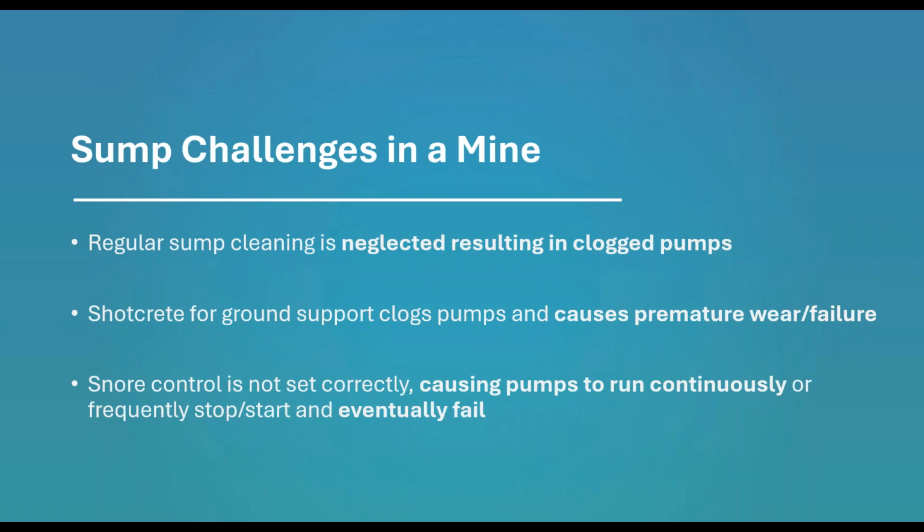We talked about wanting to avoid break fix incidences. And finally, level control is not correctly set. So essentially, the pumps are either running continuously or starting and stopping too frequently, eventually leading to a lot of failures. So these are some of the challenges that pumping equipment sees that really relate to the sumps themselves and how they're maintained.